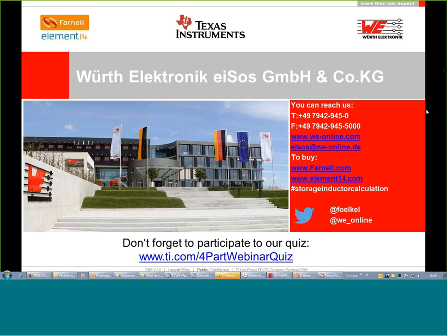Another question: in a buck topology, what would it mean if the inductor makes more noise? Well, if you make a buck topology, you will need to use an inductor. Of course, an inductor doesn't make the noise itself. The noise is not coming because the inductor is in the circuit. With the inductor, you charge energy in a non-continuous form with a switching frequency. You charge and discharge, you charge and discharge. Actually, you are generating the noise with the IC, with the topology. Or maybe you mean the audio noise. This is something different.